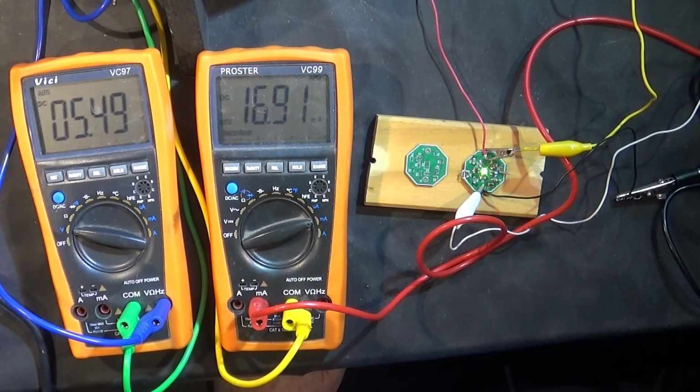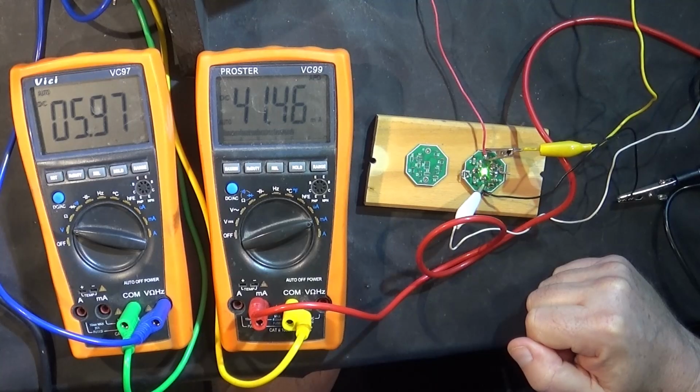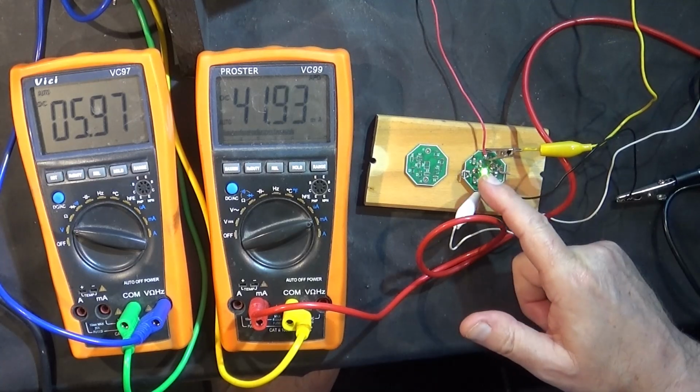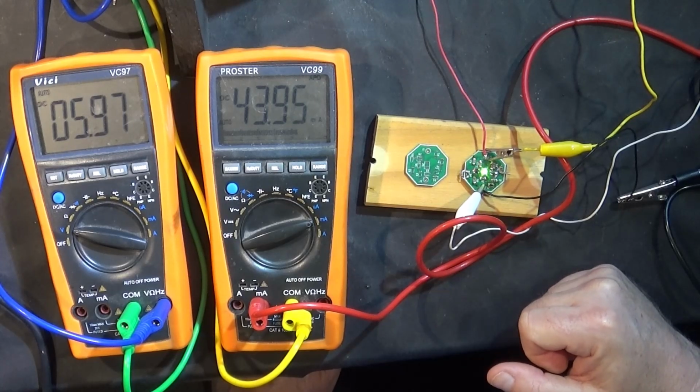And if we continue to turn it up, yeah, it's then kind of protecting the circuit, and 25 milliamps, and then it's gone over 40 milliamps. So it gets up to 5.9 volts, and it'll pull it down and empty whatever capacitors are driving it before the circuit comes to any harm. So I am happy with that also. So shall we connect up a resistor and a capacitor and see if we can make an oscillator.